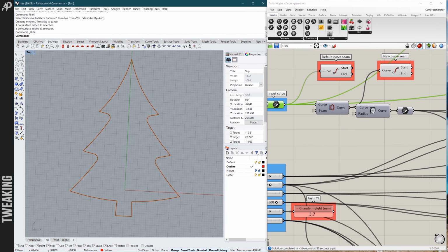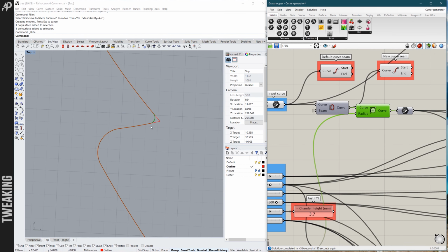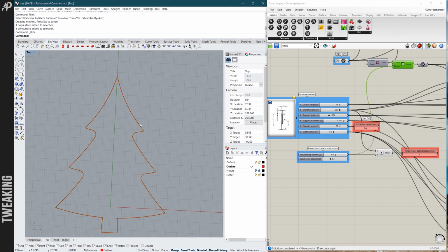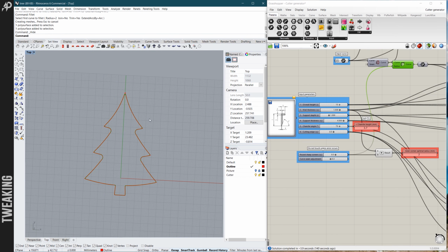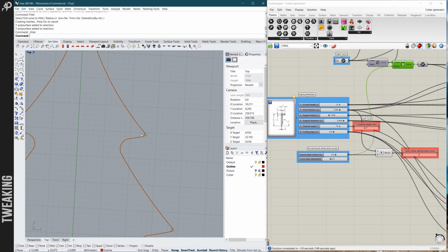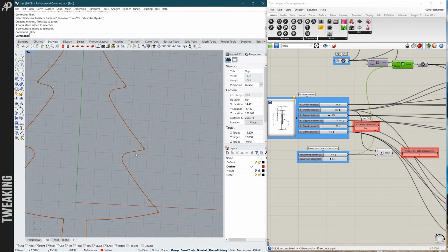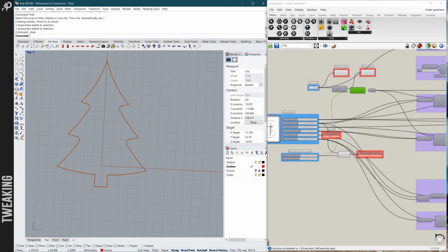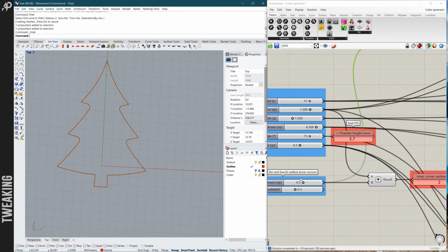And here I automatically fillet every sharp corner by the value defined here. And all of that happens for all offsets that are made later on. So if I offset it outside, and I'm doing it a couple of times, I always fillet every sharp corner of this value.